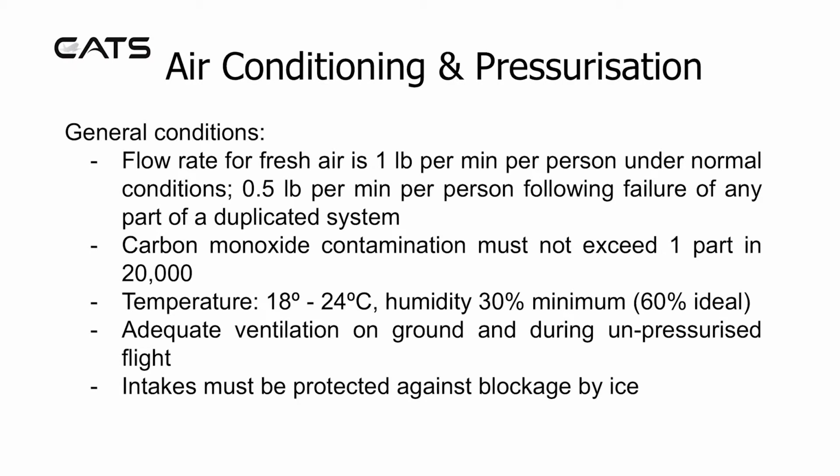Carbon monoxide contamination must not exceed 1 part in 20,000. The temperature is 18 to 24 degrees Celsius. Humidity 30% minimum, 60% would be ideal. Adequate ventilation on the ground and during unpressurized flight. Intakes must be protected against blockage by ice.